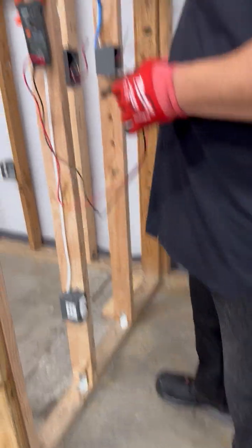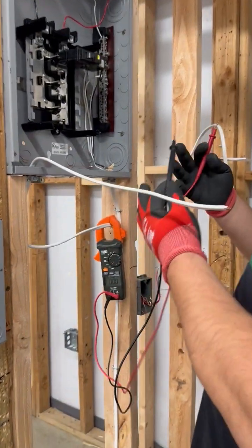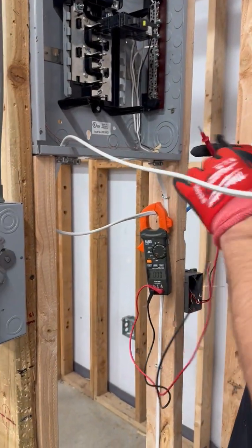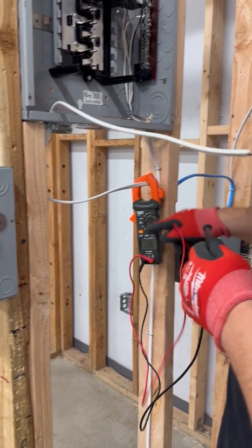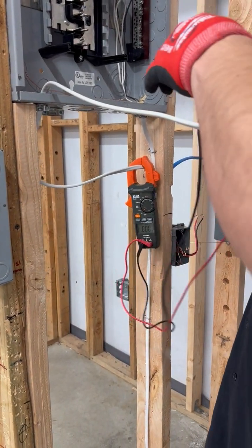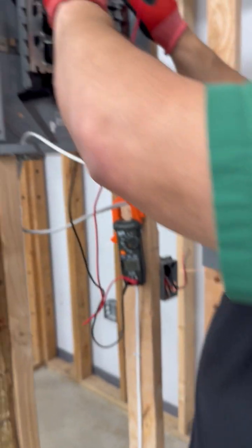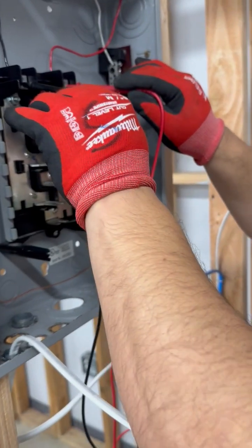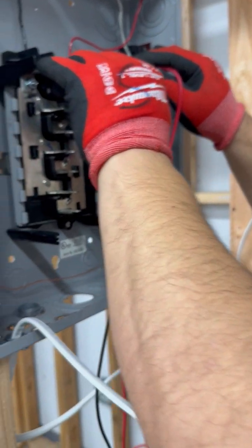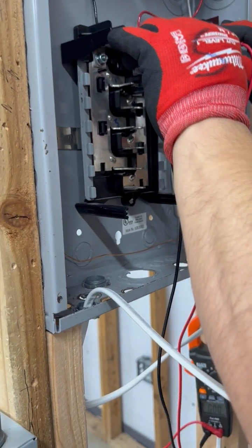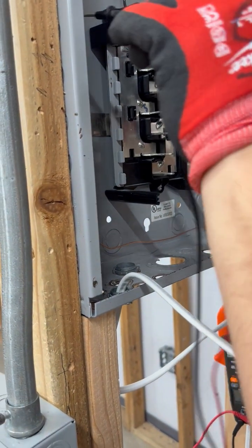So one of the things I utilize is a refresher. I'll tell them, okay, when I'm going to do a voltage check, this is where I start. I have a standard procedure. I'm going to check line to line, and I might get 208. In this building, that's the potential, 208. Then I'm going to tell them, give me a line to ground check.